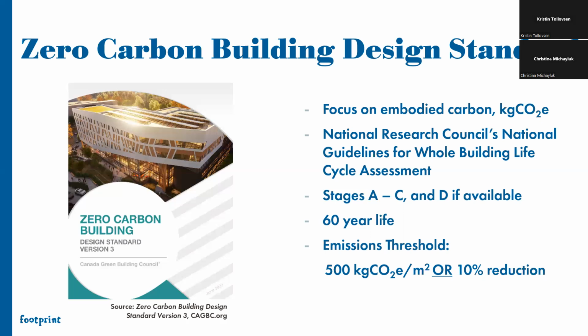So with the Zero Carbon Building Standard, we are following some really similar things to LEED, except with a pure focus on embodied carbon. We're looking at that 60-year lifespan that we followed with LEED, and we are looking at stages A through C: the product and construction stage, the use stage, as well as the end-of-life stage. But then there's stage D, which I had mentioned before, the benefits item. If the life cycle assessment program you're using has that information available, they do want you to report it. It doesn't come into your total number at all, it's just there as a report, which is fantastic.